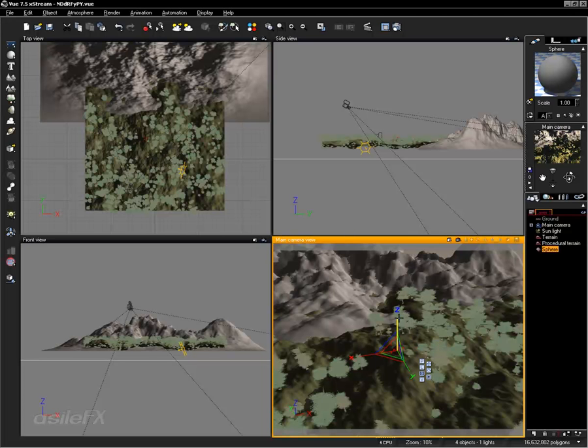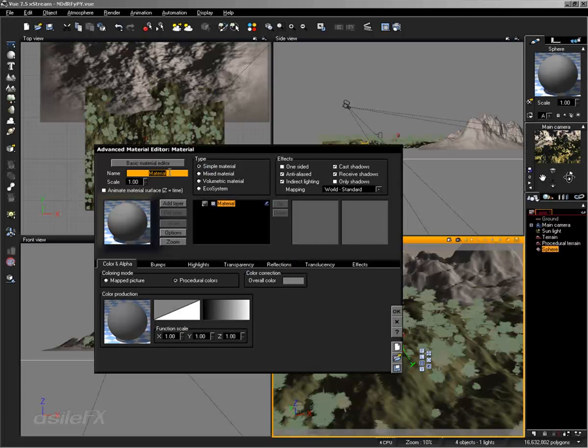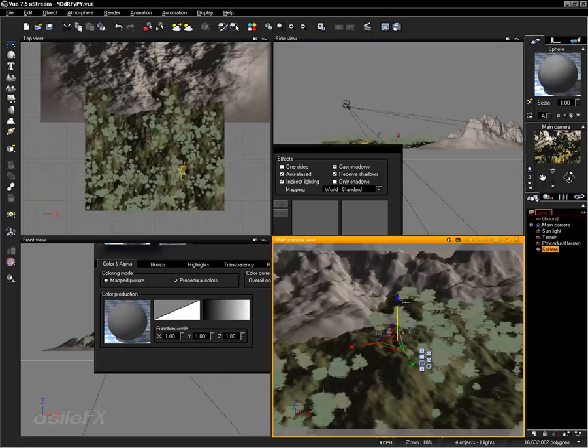First thing I want to do is just stretch it out a little bit on what I have as my z-axis, the up and down axis. And it's not really the shape of a tree, but it's pretty close. At least enough for any sort of dynamic interaction this large of a scale. I'm going to reduce that slightly. We can modify this shape more later. I am going to open up the material editor and replace this material name that is called material because I reset it with collision. And we should go ahead and call this tree_eco_collision.